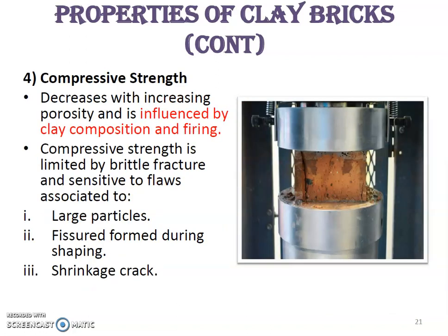And then the next property is compressive strength. The picture shows how we do the compressive strength test for the clay bricks. Compressive strength actually decreases with increasing porosity. And this strength is influenced by the clay composition and also firing. This compressive strength is actually limited by brittle fracture and sensitive to flaws, which are associated with large particles, features formed during shaping, and also shrinkage cracks.